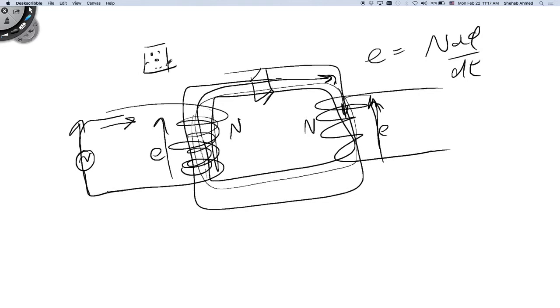You try to push more flux through it, and how do you generate flux? From current, right? It means you're trying to push more current, but it does not take. It's not resulting in flux anymore. So it's basically burning current. You're pushing more current, you're increasing the voltage, current is increasing. You're thinking that flux increases, but it doesn't, because you have limited space. The flux density of the core has a certain limit, right?